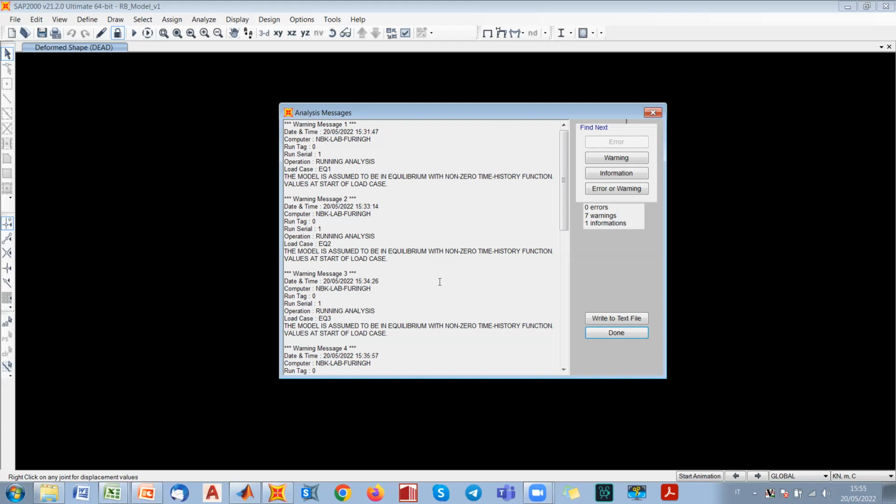So maybe we have the ordinary response for the design earthquake, but then if an earthquake occurs which is very severe and very strong, the additional hardening at a larger value of lateral shear strain provides a sort of additional strength for the overall isolation system, which tries to limit displacements, even though the intensity of the seismic event is increasing. So that is something which has to be accounted for.